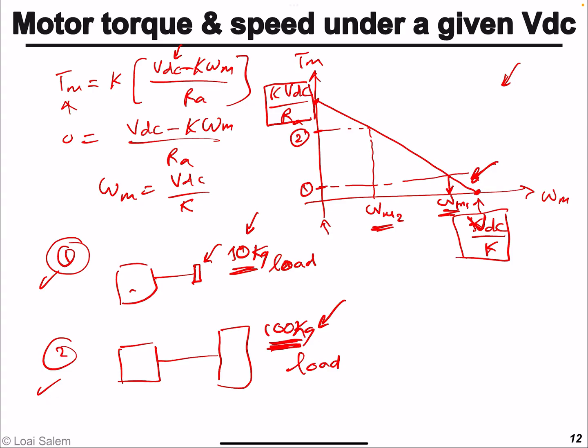So now, say we have this motor in an electric car or whatever, a toy car, because we're studying the brushed DC motor. As the toy car is moving and being controlled, it might face an increasing or decreasing surface, so we can't have a constant VDC across the motor. We need to control it. So how do we control the speed if we want to maintain a constant speed for the toy car? We need to change VDC.